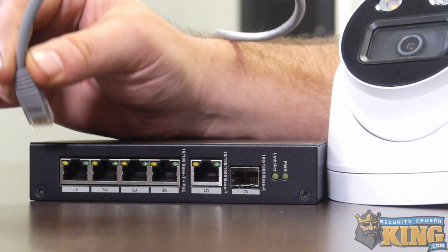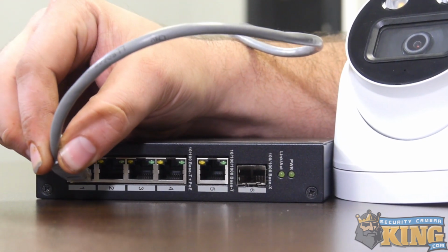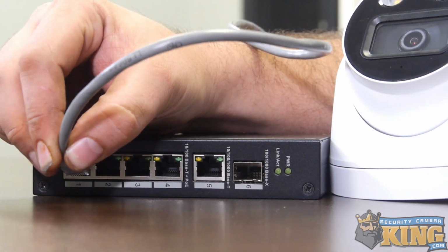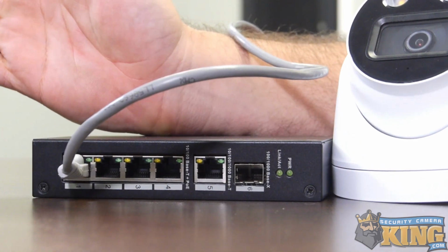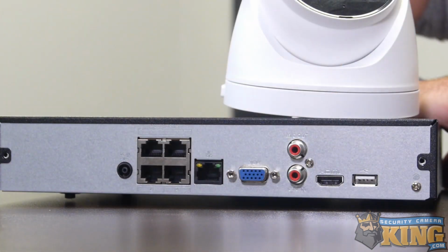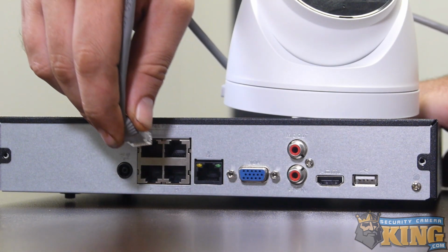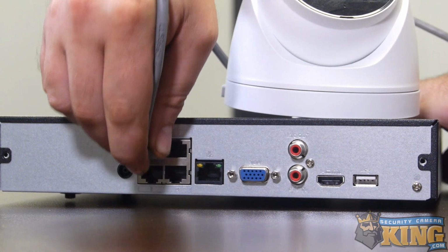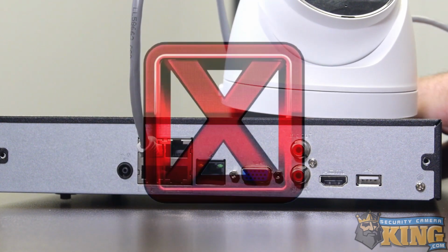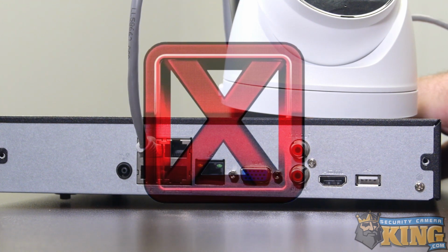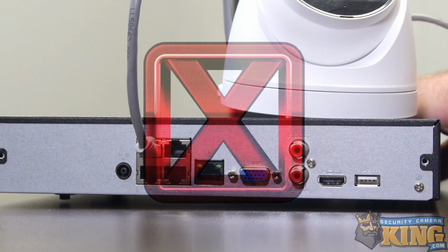Firstly, we recommend you have the active deterrence camera connected to an external PoE switch that is part of a network you can easily access, at least for the initial setup, rather than direct to a recorder's onboard PoE. This is because you'll need to access the camera directly to activate and program some of the related settings, and this is not normally possible when a camera is connected to the NVR's private PoE network. If the camera is to be ultimately used with an onboard PoE, it can be moved after the setup, but the camera will have to be set to DHCP.